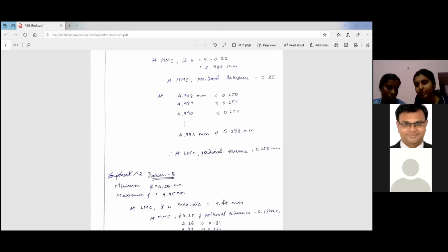And next, for the component given in the question, we'll give the circular positional tolerance for the whole, sir, and that position tolerance is with respect to all three datums A, B, and C. Okay. And for all the three surfaces, we'll give profile also, sir.